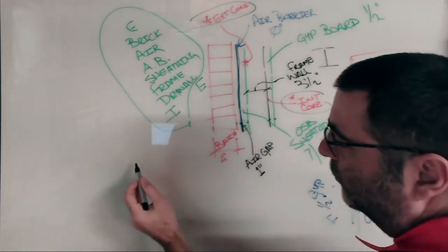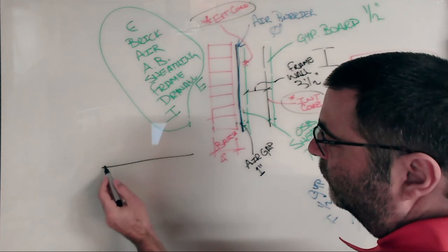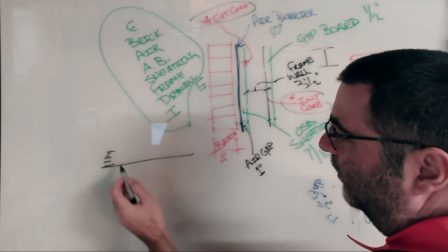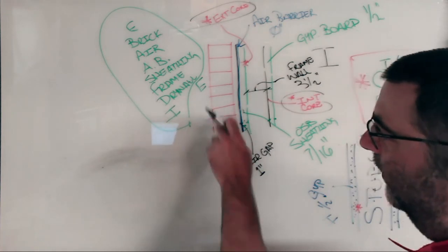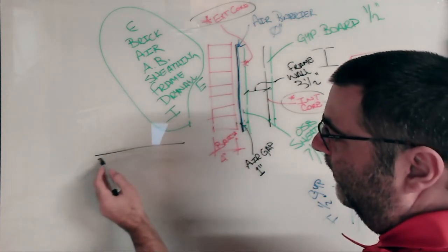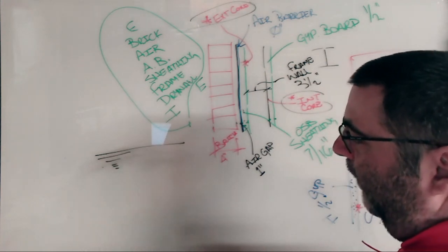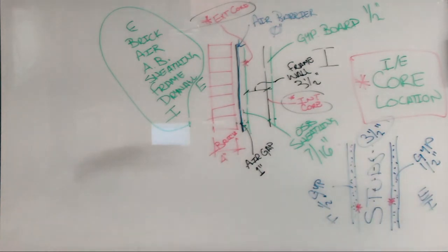So as you draw your line, you draw your wall, you have drywall and your brick will be on this way, right? The other one was finished face exterior. As you draw your line, your brick would be here, and then your interior would come this way. Okay, so they're exactly the opposite of one another.